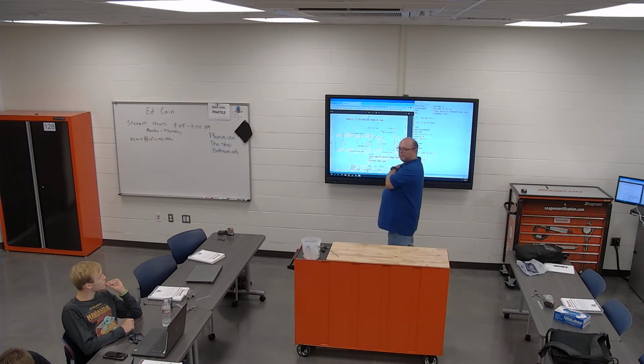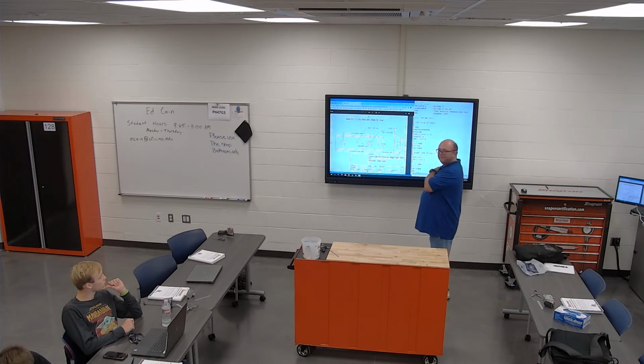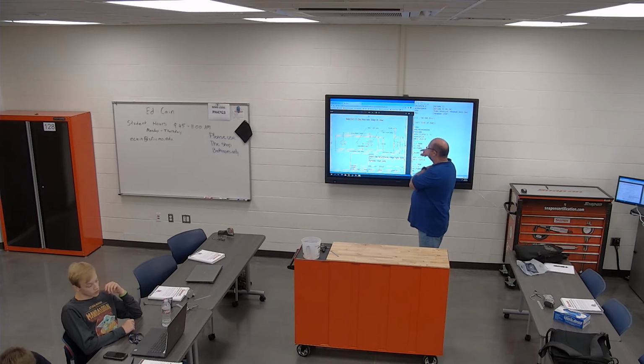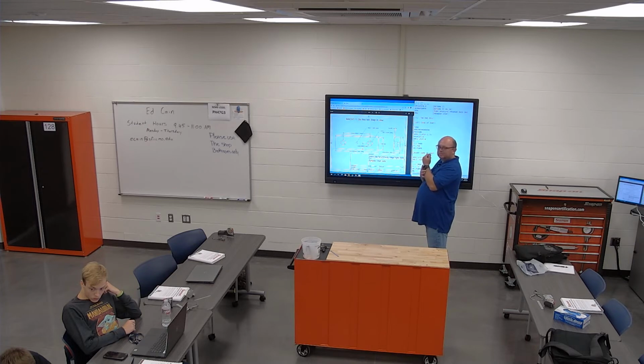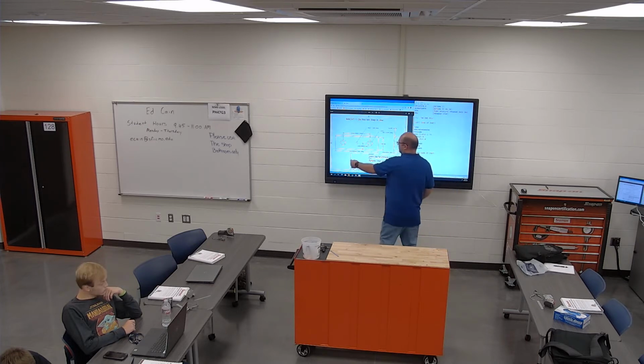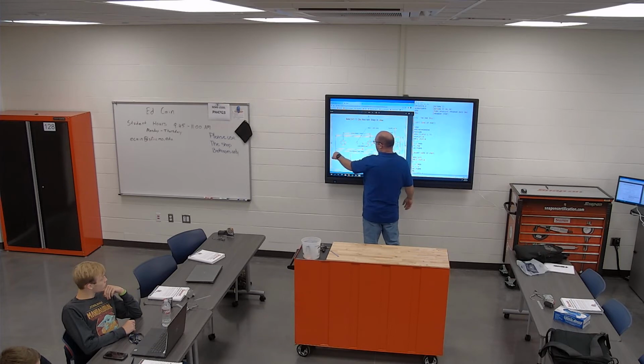And you gotta make sure you put the right correction or directions. Well, this one you program the direction by the numbers. Right now, I'm saying you wanna make sure you're climb milling, not conventional milling, right? Correct. Okay. Climb milling is this way. Conventional milling is this way.